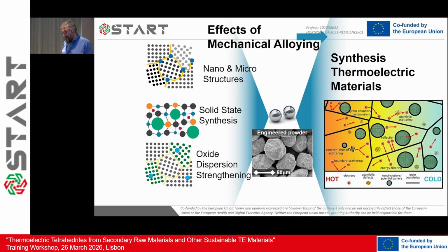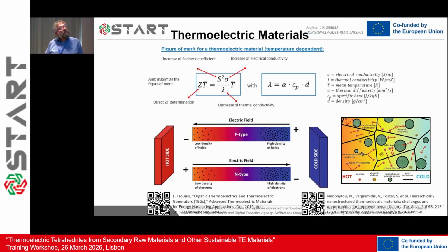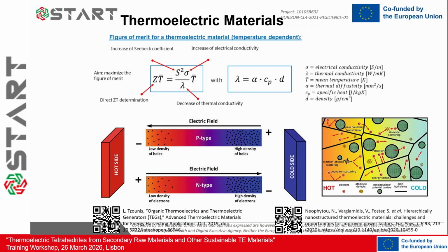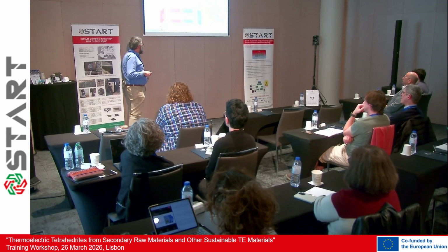electrical conductivity. So I don't want to go into the detail of this because I think you already heard a lot today about what thermoelectric materials are. I'm not the best person to go into these details, but the key point is that the effect of ball milling on the material helps also in this direction. So sometimes, even if you have a material obtained by casting, it's worth doing crushing and ball milling in order to get this nanostructuring effect that helps in the overall final properties.